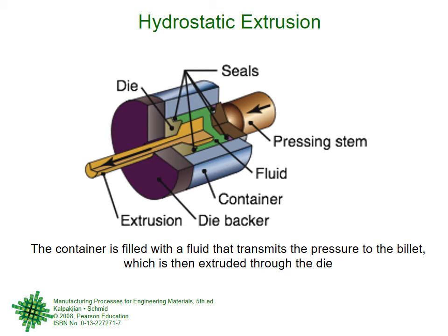But before the billet material is forced through the die, it is already in direct contact with the inside wall of the container. So at the container billet interface there is some friction. Of course, by applying lubricants and a very high surface finish on the inside of the container and outside of the billet, you can reduce the friction, but that friction is definitely there.